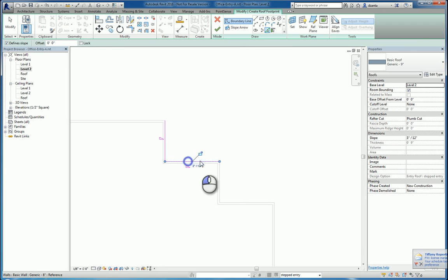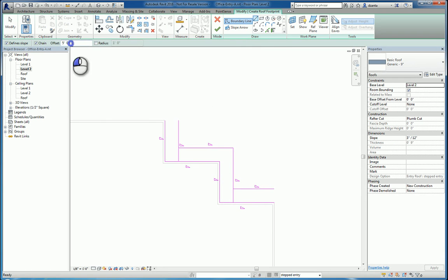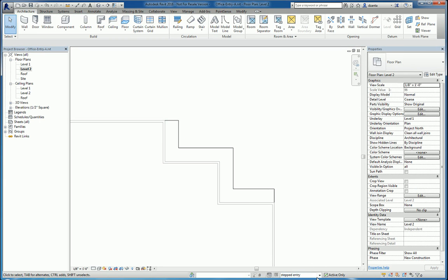Let's go ahead over to the stepped entry and do the same thing again, but this time picking it to be a stepped design. And that basically just means that we're doing it at, say, a 5-foot offset, like this. And finish the line work. Clean up the lines. Again, we want them all to not have slope. So it's flat. There's my stepped design.